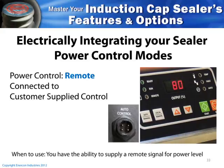The next option is remote control of your power. On the front panel, you'll see that we refer to this as auto control to differentiate it from remote start, but this is basically remote controlling your unit. With this option, you can control the output with a 0 to 10 volt signal from your process controller. This is most beneficial when you've got a central location that you'd like to control everything with. This completely removes the power control from the front panel of the unit.